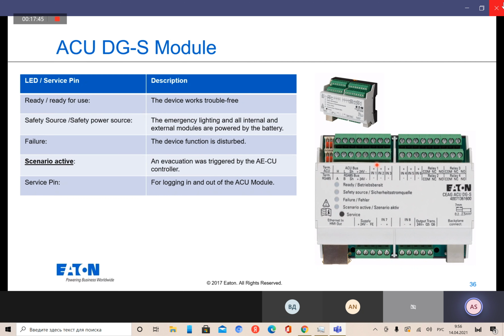These inputs, you might miss S3, S4, and S1, S2. So these inputs need to be programmed all the time. If you have phase monitoring with S3, S4 with a conventional phase monitor, you need to program it. You can say, I would like to use input number 1 as 3-phase monitoring. Then you can program it, and after you have done it, this works like S3, S4. As well, if you say, I would like to use a key switch for the system to block the device, an F3 interface, you can say, I would like to use the second input for this function, and so on. So now you are absolutely free to program your functionality to the inputs.